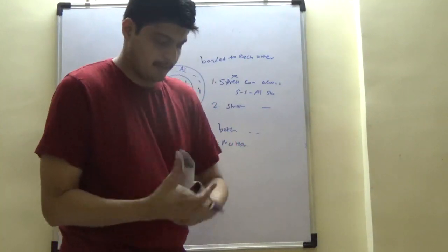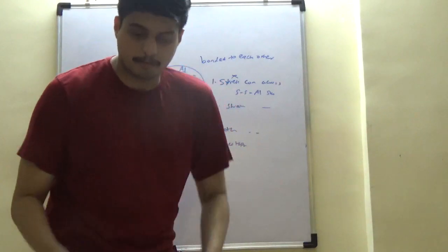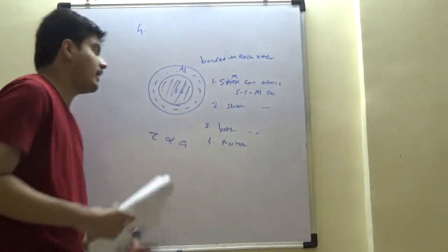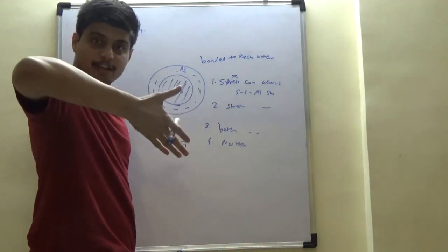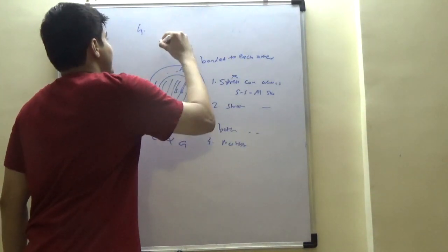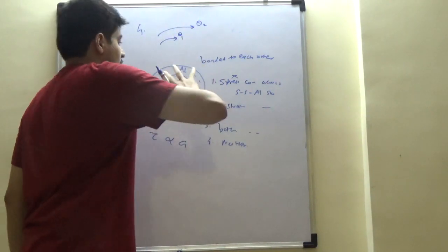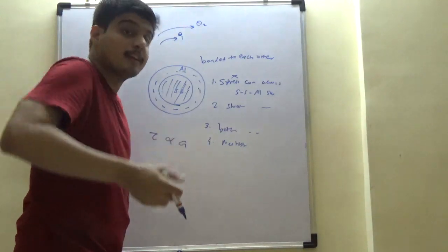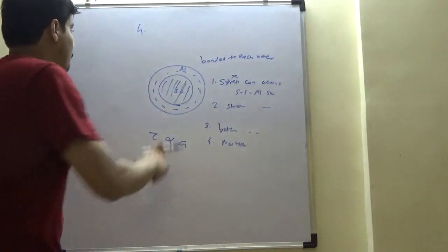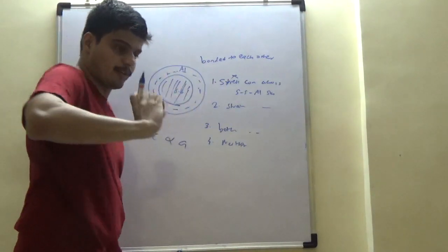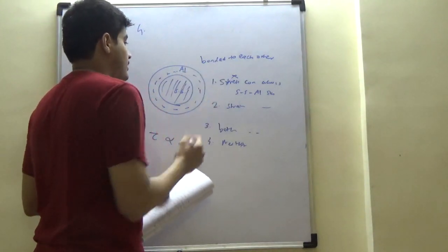If there is one bar inside which there is another bar, and these are not bonded but free to rotate with respect to each other, based on their material properties they would have different twists, different theta dash. But if SS moves by this angle theta and aluminium by theta 2, you would see a slip. The slip is not allowed, which means, depending on which tries to twist more, like a thermal problem, the second will resist. So there are going to be opposite stresses formed.